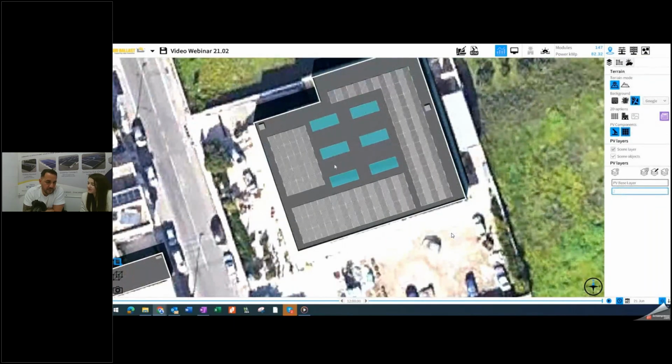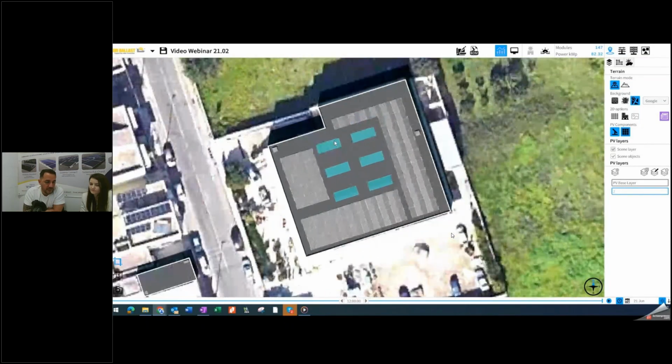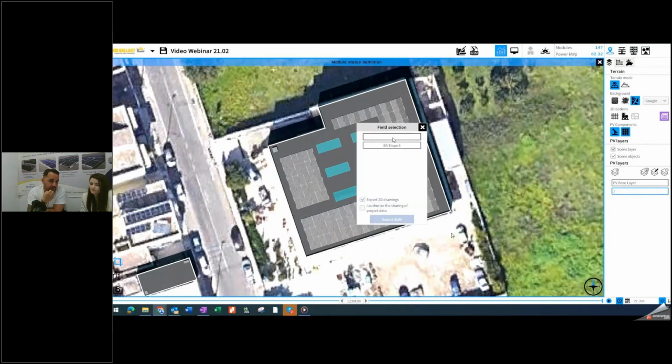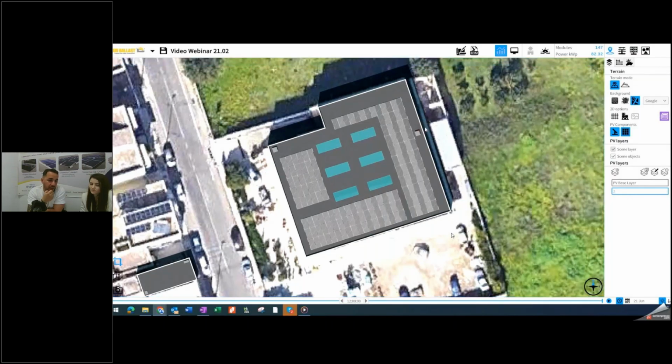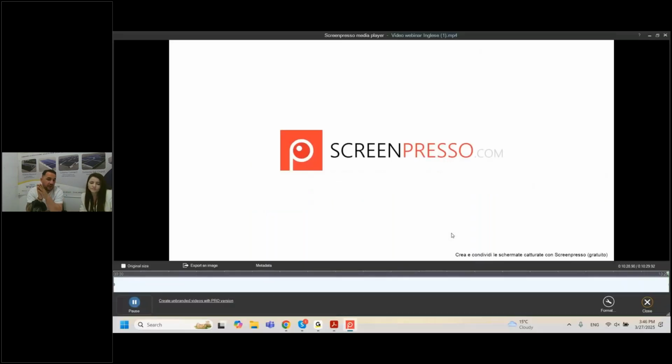Yeah, in a couple of minutes, you get the idea of the power of the panels that you can fit. Yeah, in here it's generated according to avoid shading, right? So for me, Easy West is one of the best solutions for east-west orientation, especially now with the latest generation of panel. I would definitely go with Easy West. Okay, so great. I'd like to mention that even in here you can add or remove obstacles as you want. In here, after you select them all, you can export the BOM when it's written above. So you can export the BOM. It will give you automatically the list of materials.